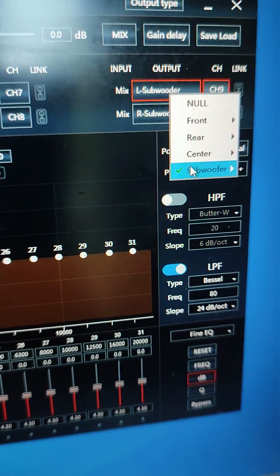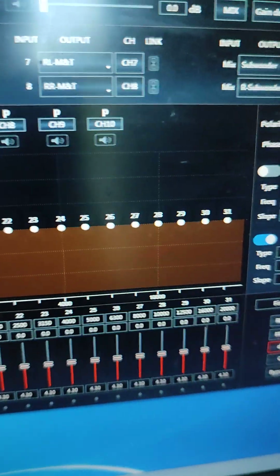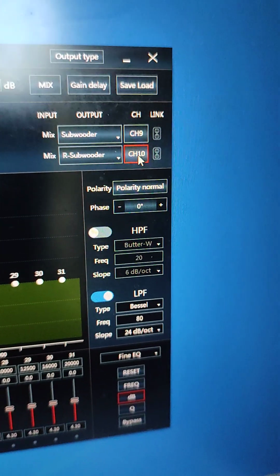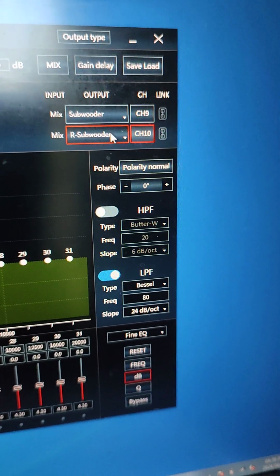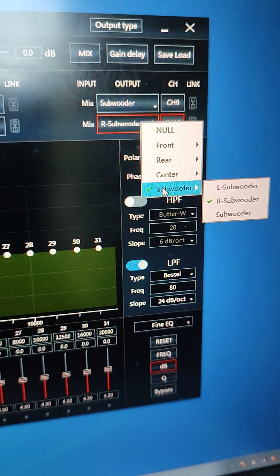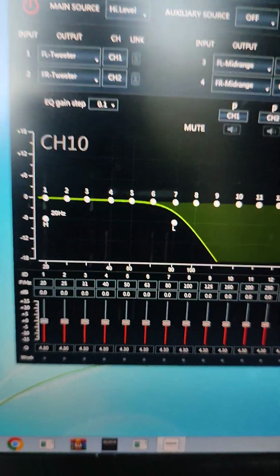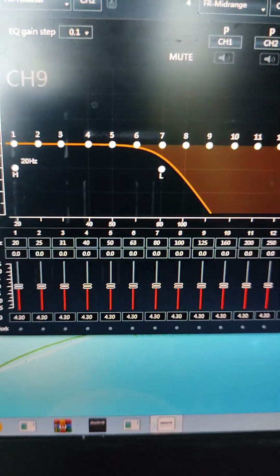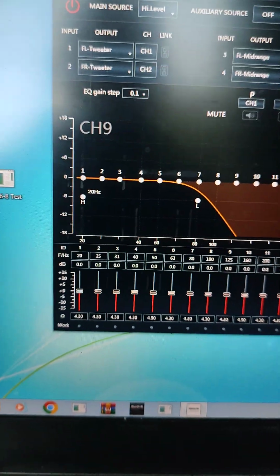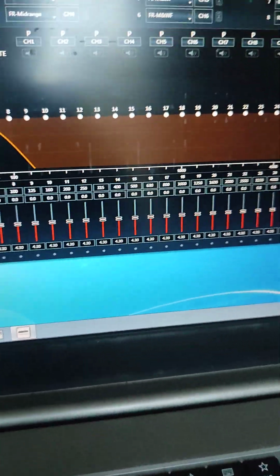Okay, so then when you choose a subwoofer, let's assume there's one in the car and it's a subwoofer. If you have two subwoofers, you can now change this to two different subwoofer outputs, and that will allow you to have a left and a right, or a front and a rear. As more and more cars are building a front and a rear subwoofer, you can use each RCA for each one. But at the moment, we've mirrored the subwoofer, and the option offered to you by the preset is 80 Hertz. So really, you've got a good guideline, and we'll go through them there.